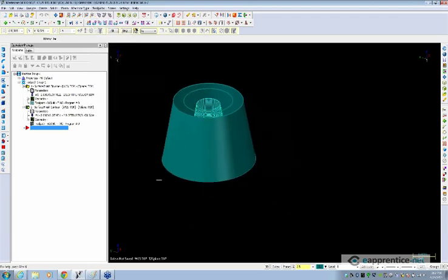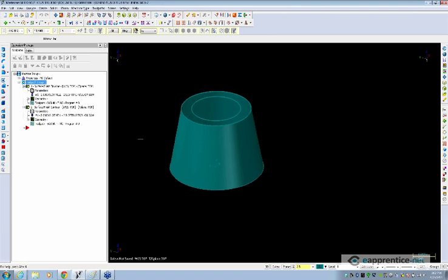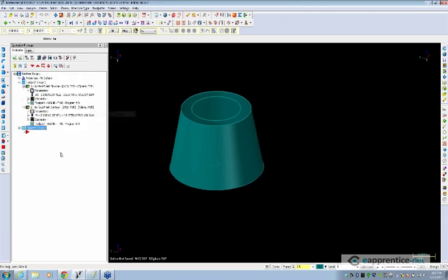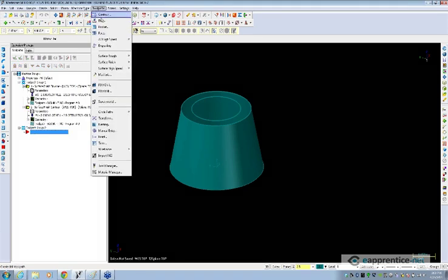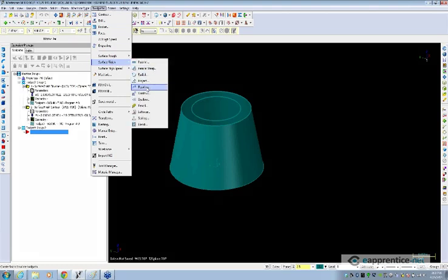So let's take a look at how we create one of these toolpaths. I've got some toolpaths already created, but I kind of think that's cheating. So what we're going to do is recreate both of these toolpaths live so that you can see how I'm doing it. Let's create a new toolpath group just to help keep them separate. And now I'll select Surface Finish Flowline. Now in order for Flowline to work,